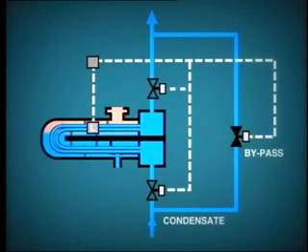In some installations, the high water level causes the condensate to bypass the heater altogether by automatically operating the motor-actuated isolating valves in the following sequence. Open bypass valve and then close inlet and outlet valves. The matching of extraction steam flow to the heater and condensate flow through the heater takes care of itself automatically. As more condensate is pumped through the heater, more steam is condensed, so reducing pressure and pulling more steam from the turbine. In operating closed feedwater heaters, the operator must be sure to check that venting and drainage of the heater is functioning correctly.